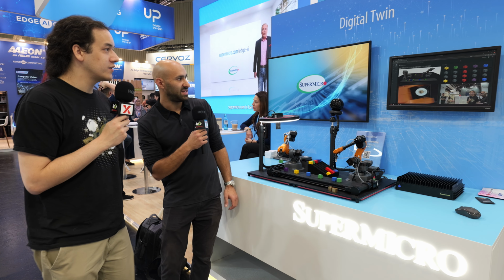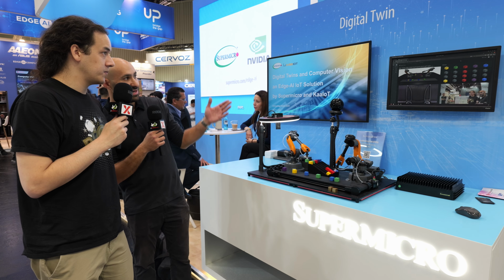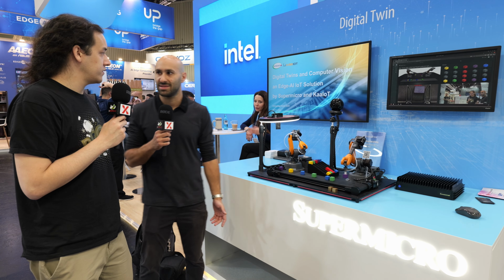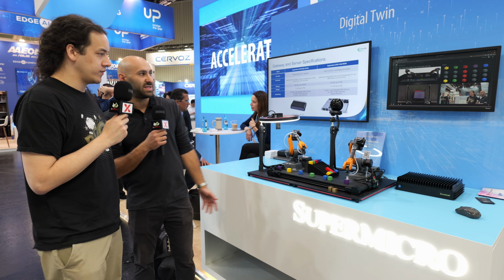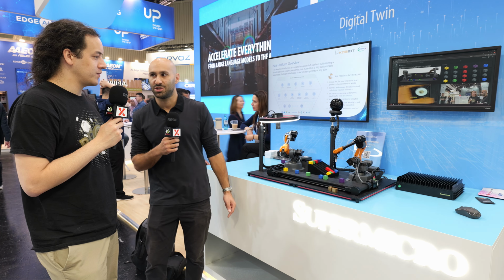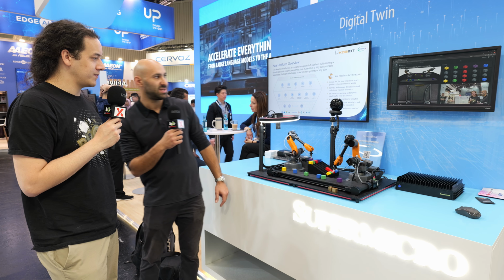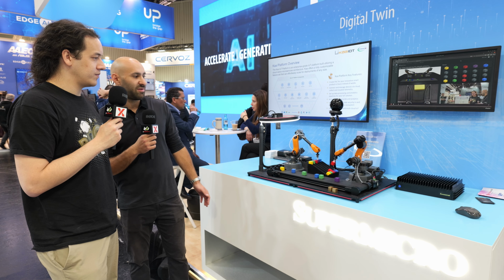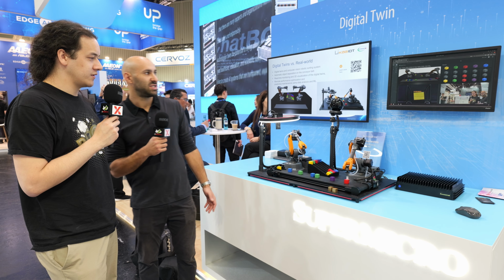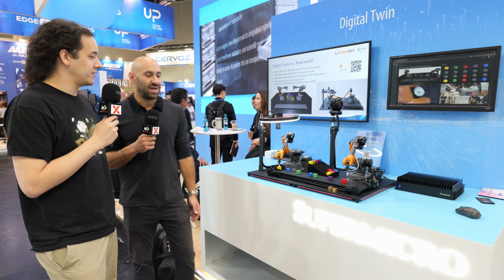One of the interesting uses of the data from these arms is to do something like predictive maintenance, where you can see under what conditions something broke, like how many hours, what temperature, what configurations, and with that data you can figure out when things are going to break in the future. Cool. And as you get more data, your predictions become more accurate.